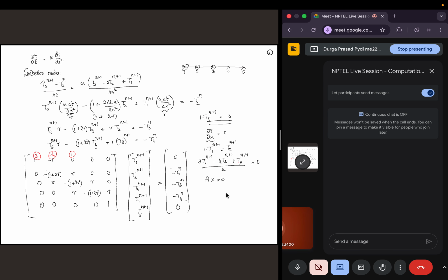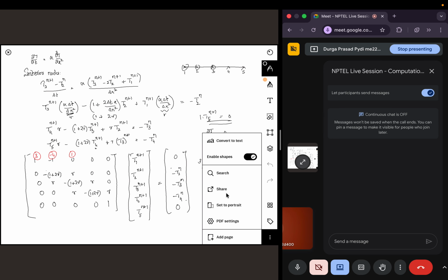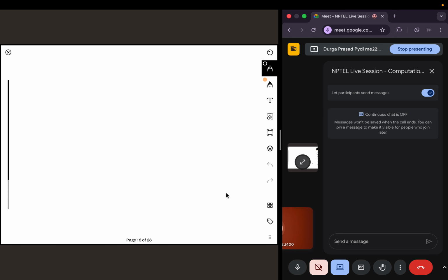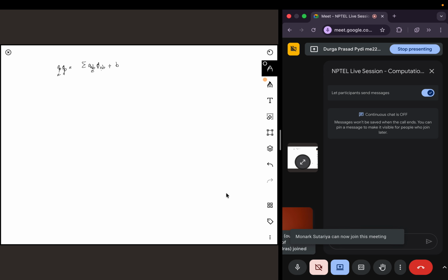Because as far as I've seen, at least from what I used, though I've not used a GPU one, all of these equations reduce to something like this. It's an infinite volume or something. Even if it is unstructured, it is basically this one. All you're trying to do is, you will know these coefficients, but they will not be constants, where phi is a variable at the current index and this will be the neighboring point and p is some constant. And all you're doing is trying to solve this equation, right?